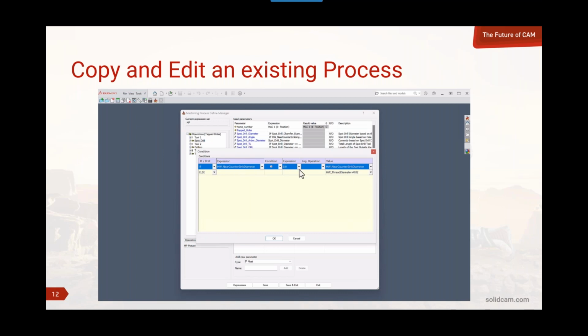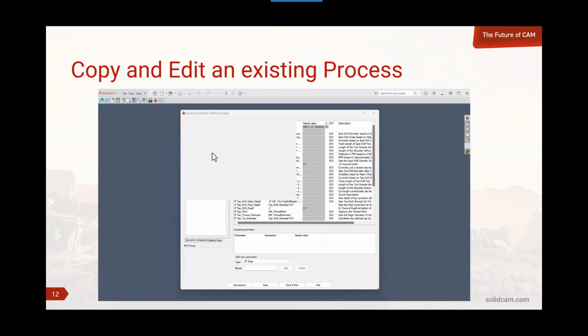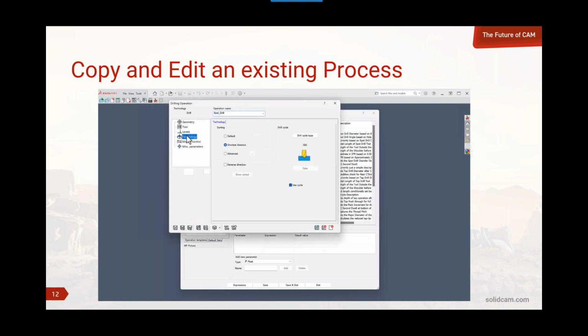If it is not greater than 0, it means that the user didn't put a chamfer on top, but I still want one in my machining process, so I'm going to grab the thread diameter, and in my case, I want to add 20 thousandths to it. You might want to add 1 millimeter or some other value. It's really easy to do, okay? And so it's very, very simple to go through these and figure out what these are doing.